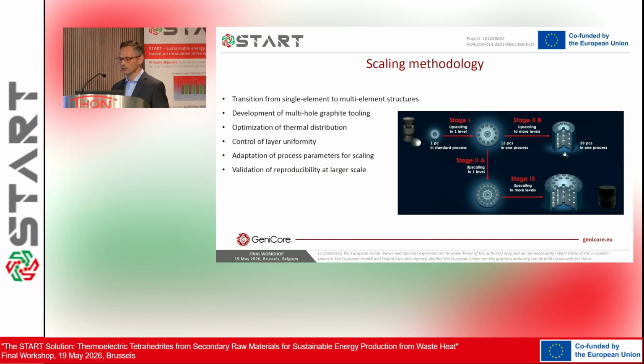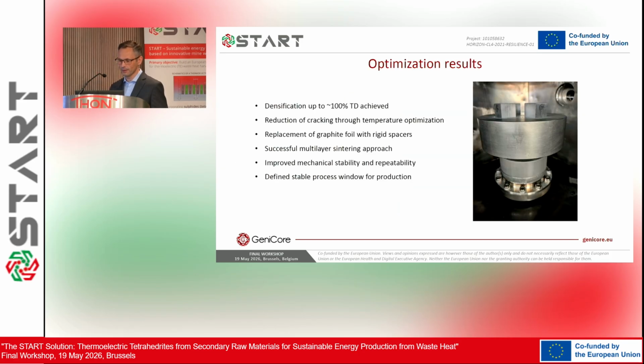The next one is incorporating additional layers of the material being sintered step by step, second one, third, and so on. Maximum what we have in our production is 5 layers, where almost 65 elements in one process can be produced. There is some limitation, for example, the size of the vacuum chamber or the total height of the pellets we put into the graphite die.